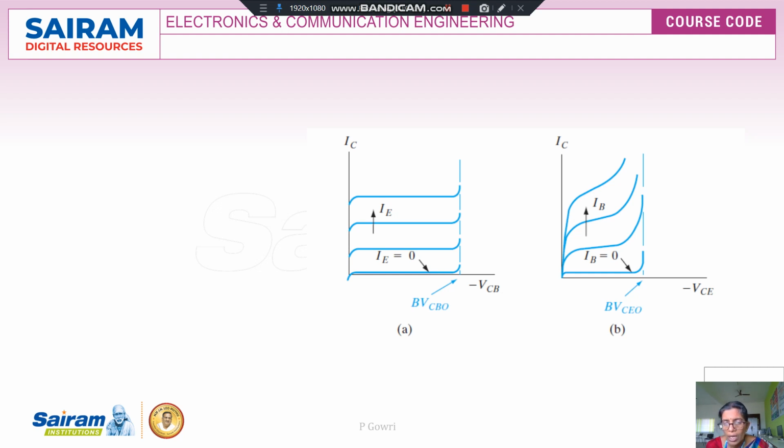What is meant by avalanche breakdown? Avalanche breakdown is when a strong electric field is developed inside a reverse biased junction in a diode. That will result in exertion of force on the charge carriers. These charge carriers, when they enter the space charge region, attain extra energy, and while moving through the lattice structure will collide with it and generate electron hole pairs. These electron hole pairs will again attain sufficient energy to create other free charge carriers. This phenomenon is a multiplication process, and hence it results in a larger number of charge carriers, and may result in an increase in the current of the output device during reverse bias. This phenomenon is called avalanche breakdown.